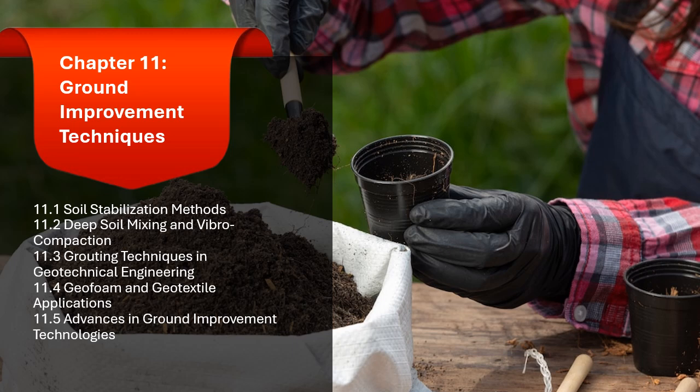1.3.3.6 Sinkhole and void remediation. In areas prone to sinkholes or ground subsidence, grouting can be used to fill voids and stabilize the soil. The grout is injected into cavities, fractures, and voids to solidify the ground, preventing further subsidence and potential surface collapse.